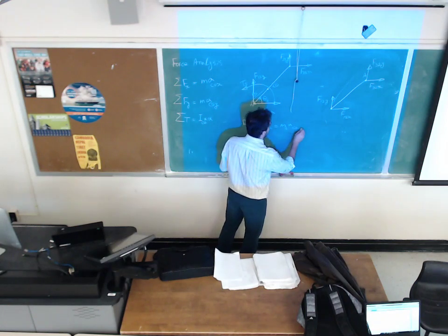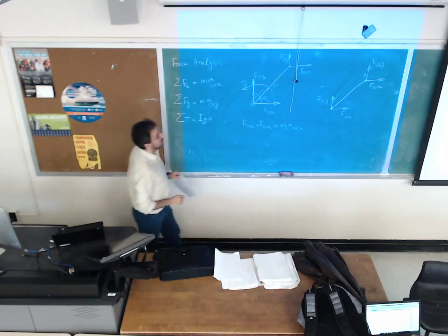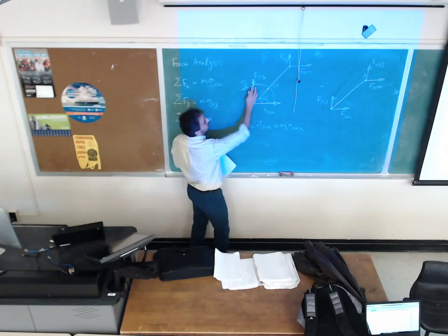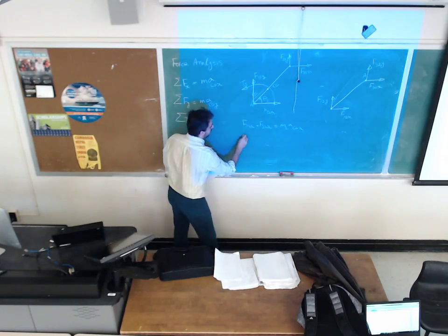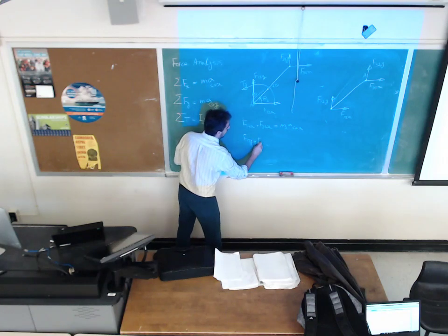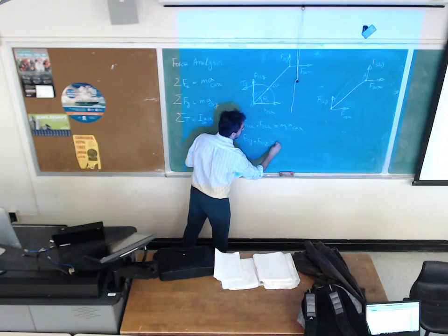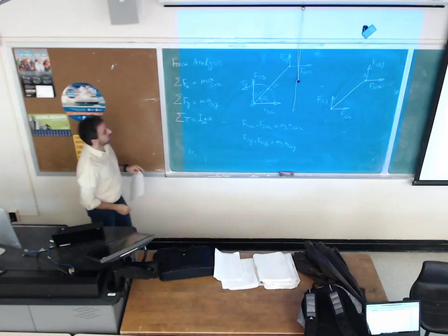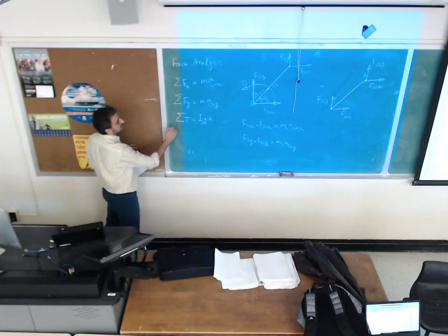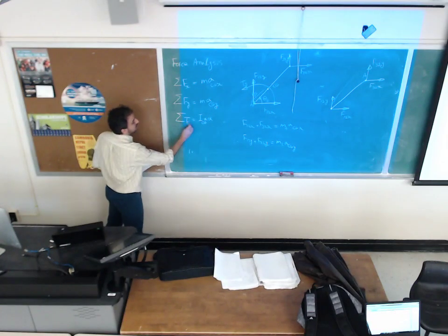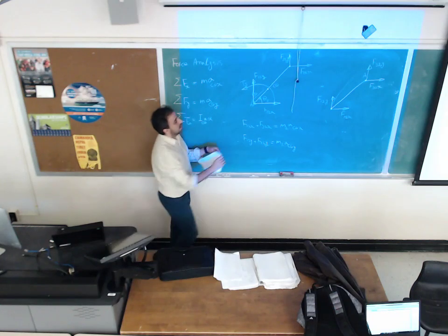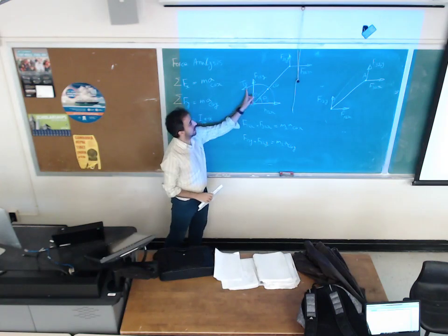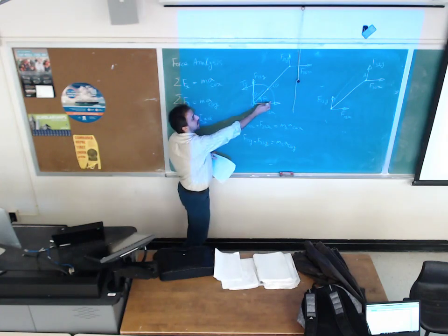Second equation, the only forces that I have in Y direction are F12y plus F32y equals to M2 times acceleration of center of gravity in Y direction. Summation of the torque with respect to center of gravity. On the left side, I have external torque coming from the motor. I assume that it's going counterclockwise, so T2 is going to be positive in the equation.